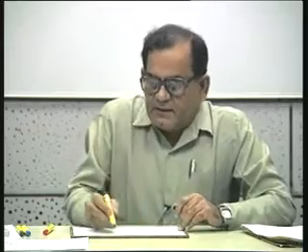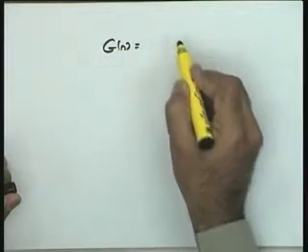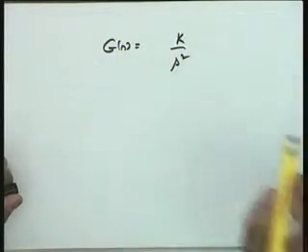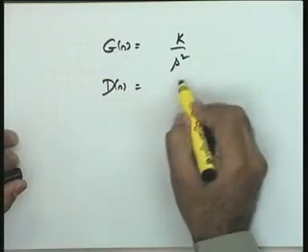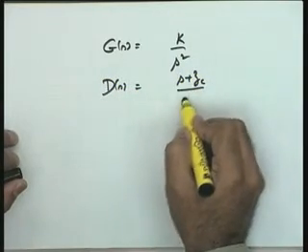Okay, fine. So in this particular plant, which is the plant of an attitude control system for a satellite, the uncompensated system I will say is K by S squared. This is an uncompensated system, and Ds, the compensator, is (S plus Zc) over (S plus Pc).